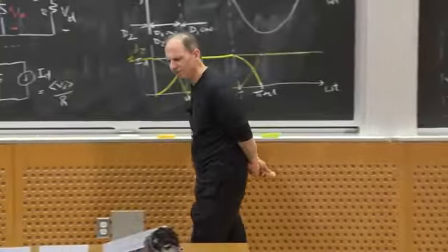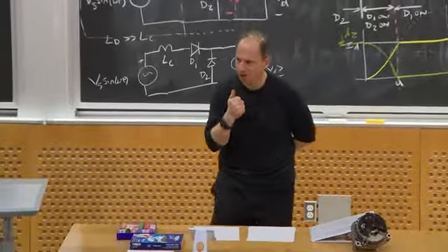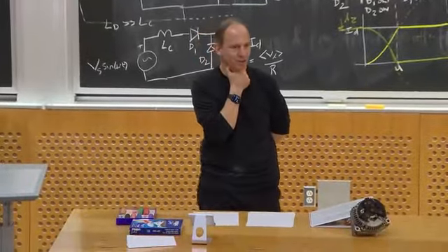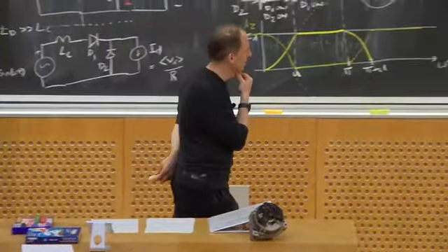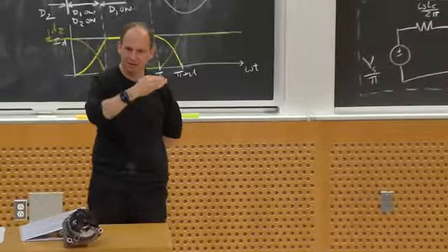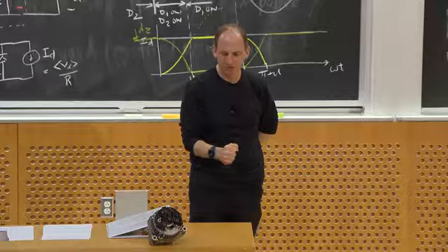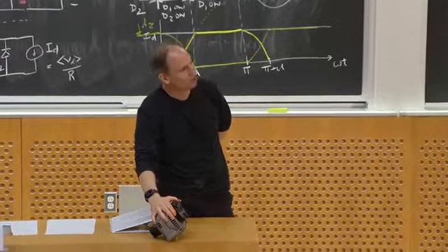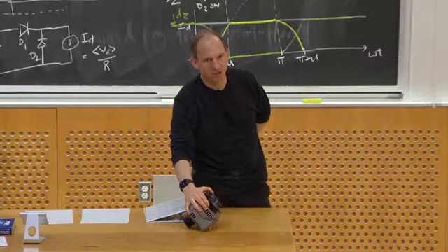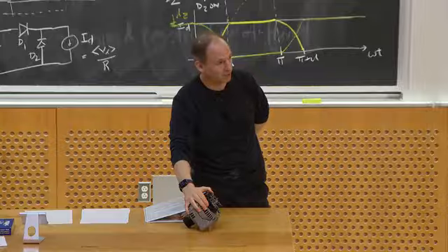Okay? But it influences all kinds of things. I mentioned we had the problem with the high-frequency resonant converter we built. Or if you were thinking, I'm going to rectify the line voltage to get a voltage I know out, and I'm getting droop, I probably don't like that. That shows up in a big way in these automotive alternators. It turns out that the reactance is really, really very big.